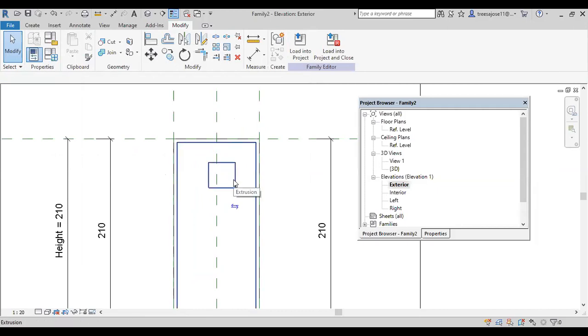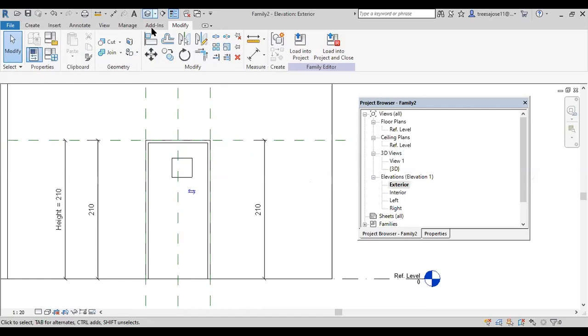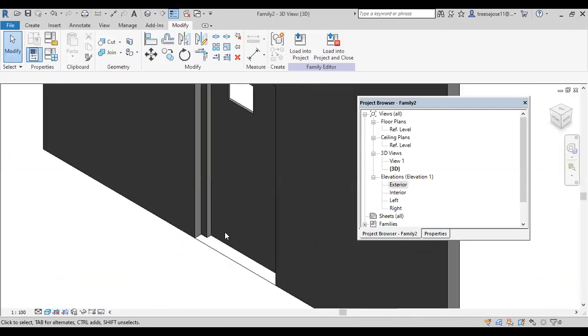Or maybe it remains constant, so you lock the dimensions. If you lock all three, changing the parameter will not be possible. Sometimes in your design you need these two to be constant, so it is better to lock them. Go to the dimension and make it locked, as I said earlier in the levels and all. Whatever changes may be, then you check it out.